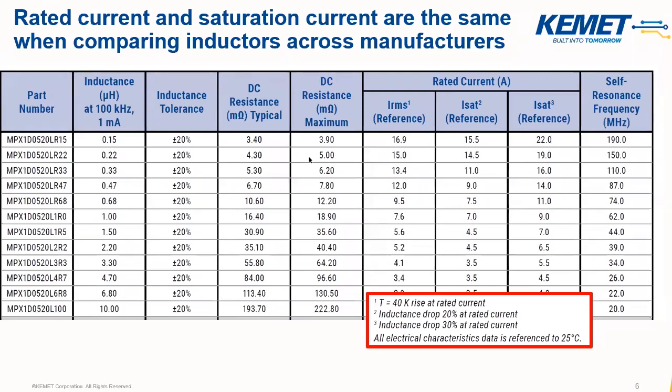And I remember one, it happens a lot of times, but you may have two inductors, same inductor value, same equivalent dimensions, and similar construction, and vendor A will have a lower DC resistance than vendor B, however vendor B would have a higher current rating for the component.